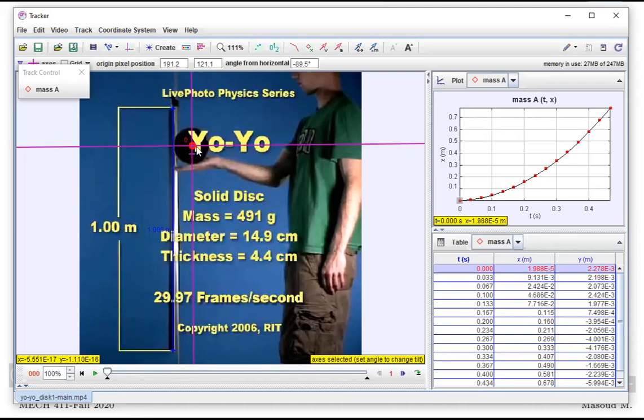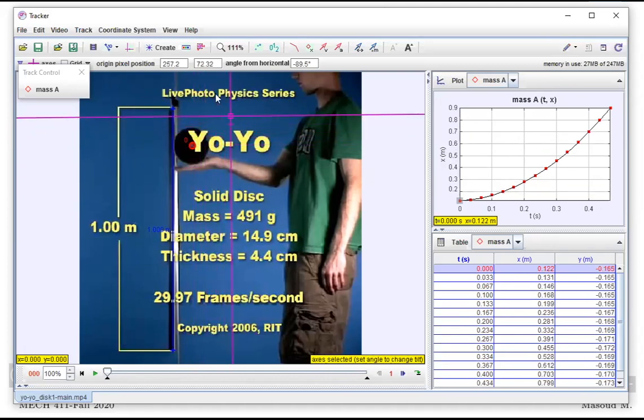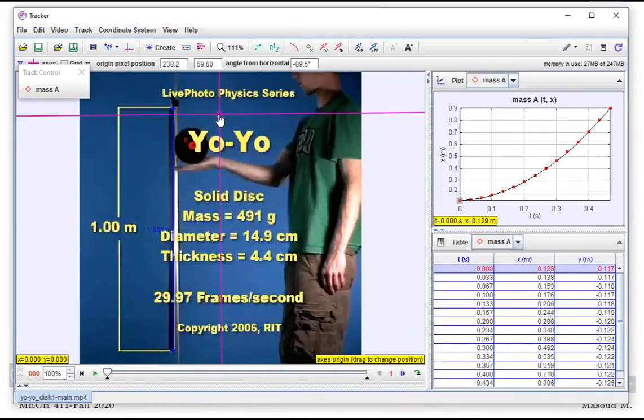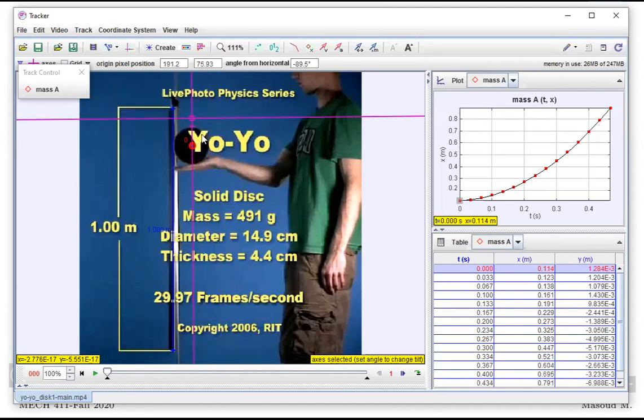If you do that, follow what happens on the plot on the right side. Right? You see the range for the X changes when you change the coordinate system, because it measures where the position is with respect to that. So if I just put it somewhere here, let's say, so it's starting from some random point. Now, how can I set it on 0? I want it to be at 0. Let's say I want the coordinate be exactly where the motion starts. In some cases, you will need that when you're looking at a spring mass system later on for projects.